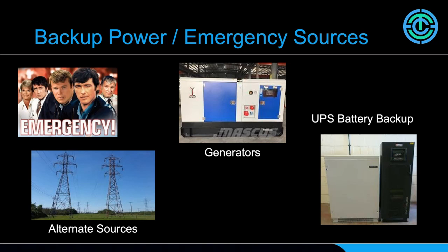So you'll have many venues that actually may have both. They've got a large load generator for long runtime operation that is exterior to the building. They'll have an interior UPS battery backup system that allows for, we'll call it ride-through conditions, where it gives them 30 minutes of uptime. And there's quite possibly systems that have only one of those or a combination of both systems.